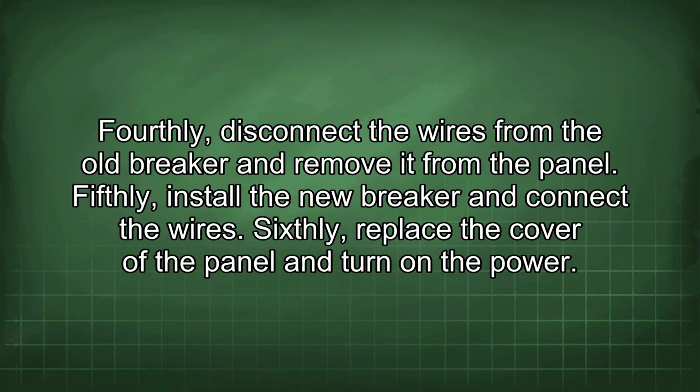Fourthly, disconnect the wires from the old breaker and remove it from the panel. Fifthly, install the new breaker and connect the wires. Sixthly, replace the cover of the panel and turn on the power.